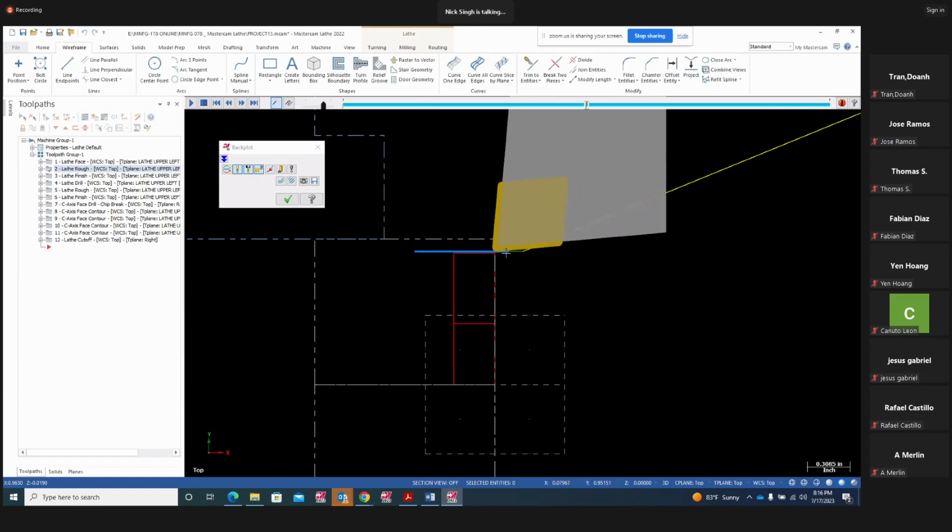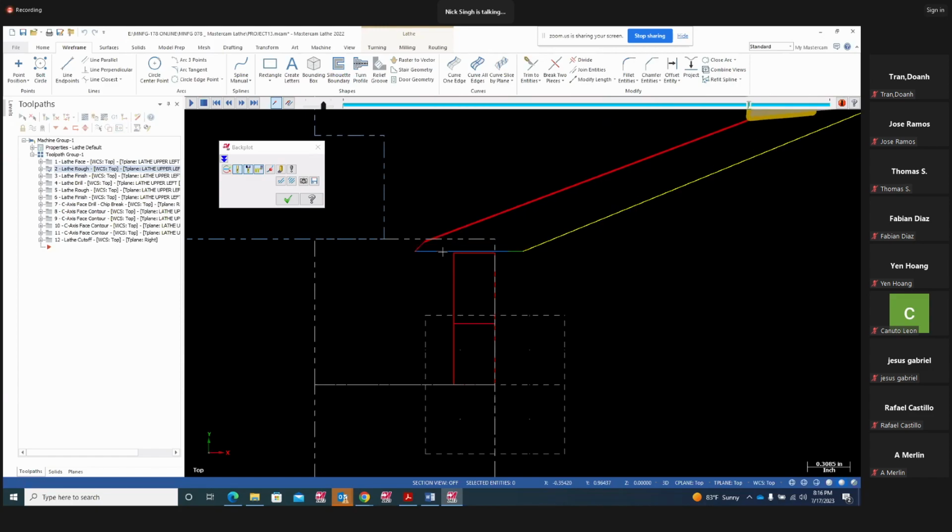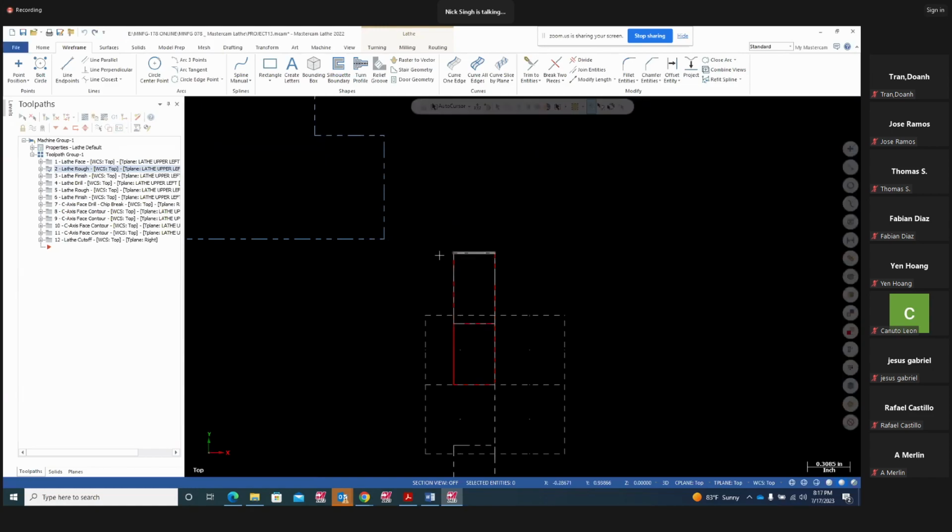There you go. Look at that. It's coming 250 out here. So we go extra on that, rough and finish both. So this is something you guys have to do. So that's that tool. Then rough here, and then your finish, and then drill.